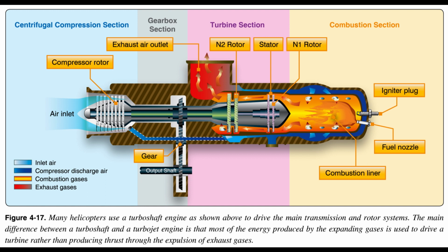This is felt throughout the airframe as vibrations and is accompanied by power loss and an increase in TOT as the fuel control adds fuel in an attempt to maintain power. This condition may be corrected by activating the bleed air system, which vents excess pressure to the atmosphere and allows a larger volume of air to enter the compressor to unstall the compressor blades.